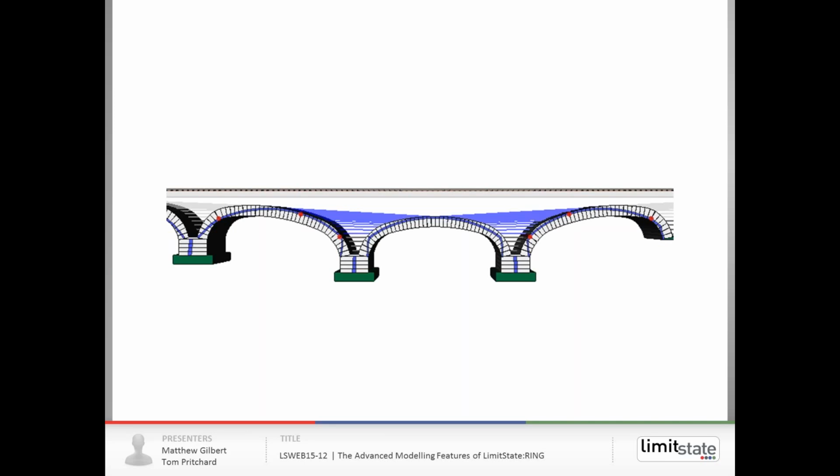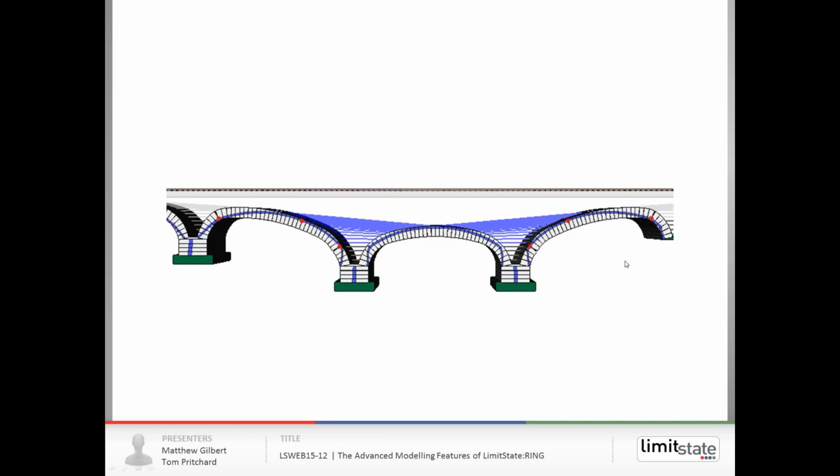If you have the same kind of bridge repeated on other stretches of the line or road, that effectively gives you an opportunity to develop a more informed model for those other bridges, if they were constructed at the same time with the same materials. So in other words, it can be considered like a free lab test of your batch of structures, if that makes sense.